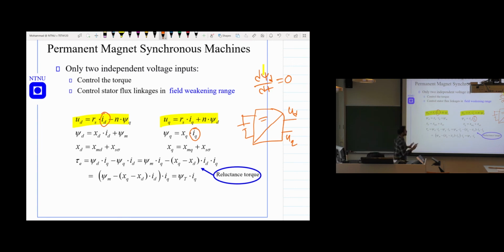In regular operation, we will mainly focus on the Q-axis current because this Q-axis current gives us the torque. If you remember the electrical torque equation, it gives us magnetic flux multiplied by IQ, and this is what gives us the torque for the symmetrical machine.